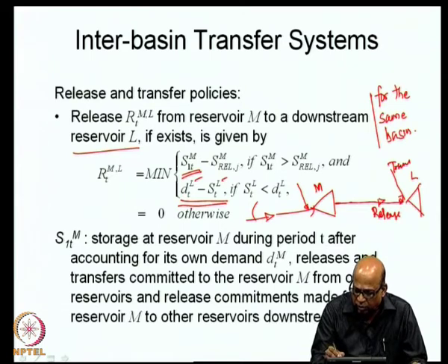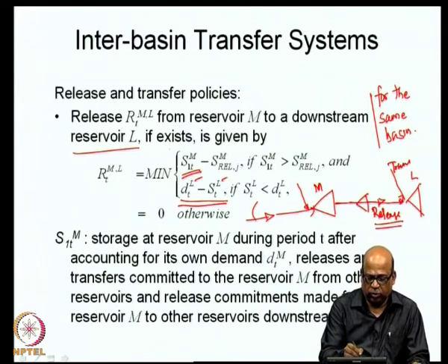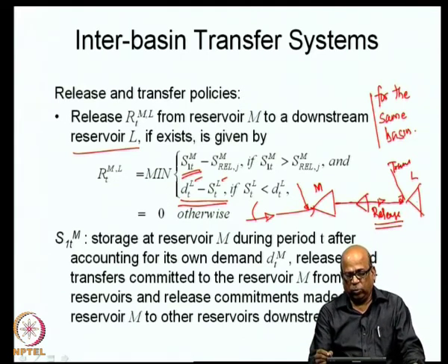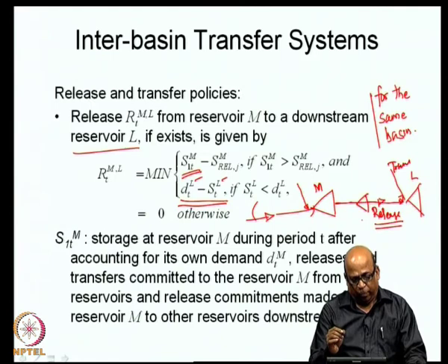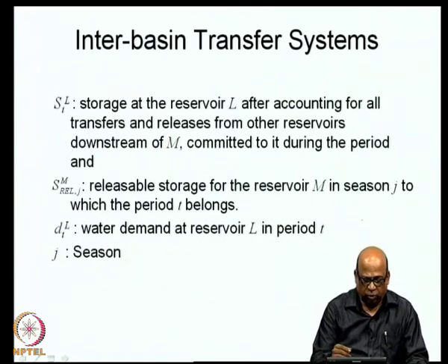By release, I mean the amount of water released to meet the requirement of the downstream reservoir. So, that is what we look at. So, that is what this says. And if there is no deficit here, you do not make any release from reservoir M to reservoir L. Much the same way, we talk about